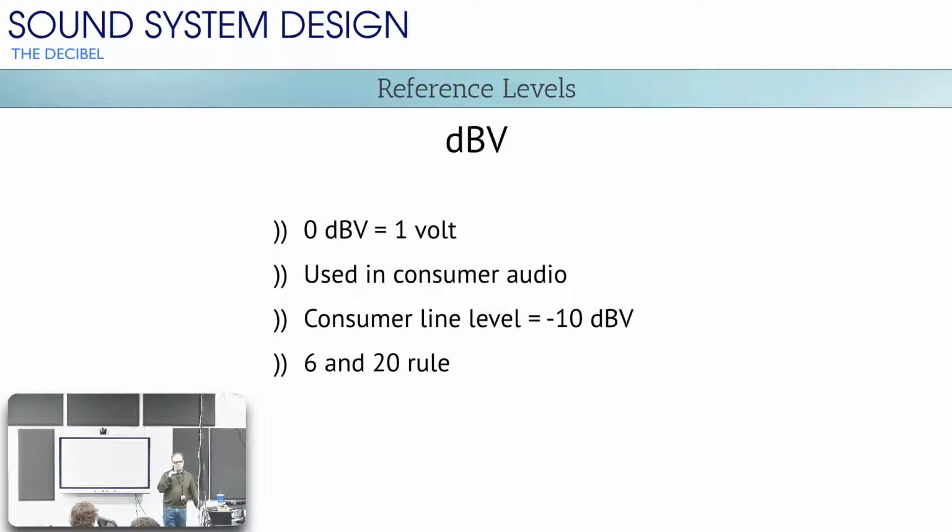if you just take whatever the source is and shoot it straight out without any attenuation or amplification, what comes out of that connector will be minus 10 dBV. That's minus 10 dBV is 0 on the meter, unity on the meter for the device. Okay, that'll be minus 10 dBV. And you can calculate that actual voltage if you want in a minute.